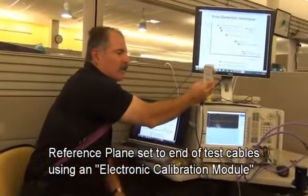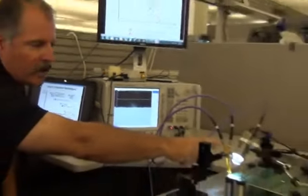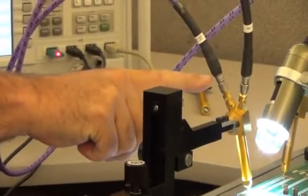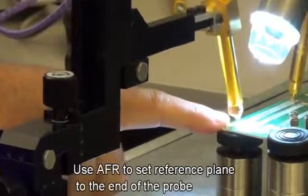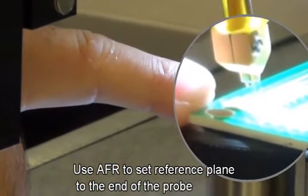So to be more specific, what we've done here with this system, we've done first an SOLT with an ecal. So we've done a short open load through to the end of the test cables. So we've got a coaxial environment with SOLT. But what we really want is the reference plane down here at the end of the probe tip. And so here, we're going to actually use AFR.